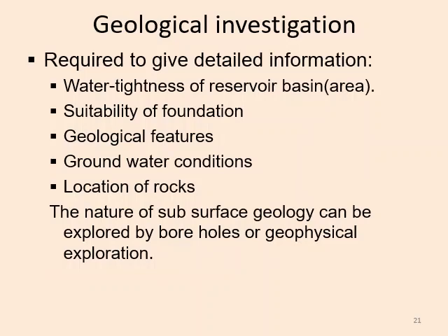Geological investigation. Why will we do a geological investigation? Because we should first know some information about the geology of that reservoir area or dam area, like the water tightness of the reservoir area. Basin and area are the same. Second is the suitability of the foundation. The foundation should be strong, so we need to find where we will get rocky mass or soil with a strong foundation.